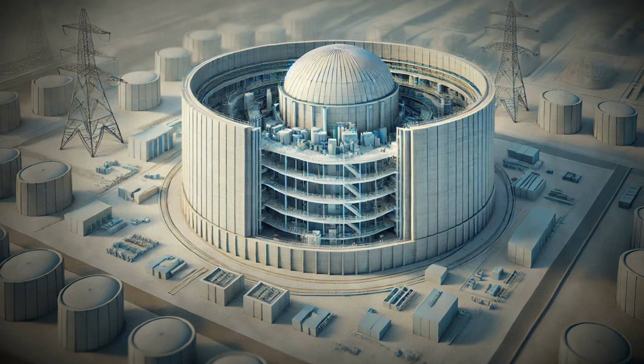Another key safety feature is the cooling system redundancy, because heat continues to be generated in the core even after the fission reaction is shut down, called decay heat. Emergency cooling systems are in place to ensure that the fuel rods remain submerged and cooled at all times. These systems often include multiple independent pumps, backup power supplies, and passive cooling mechanisms that can operate without human intervention.